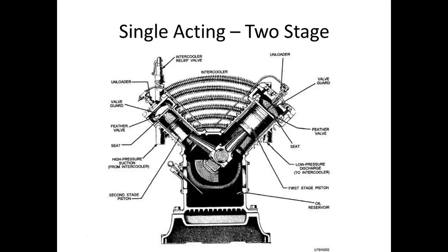These are just the part. By the way, this is in the cylinder. You can see this. What we need to do, of course, is, so you've got multi-stage compressors. They will always have an intercooler. What's an intercooler? That's a cooler between stages. Of course, here they're sending it through a pipe, and then the pipe has a bunch of cooling fins on